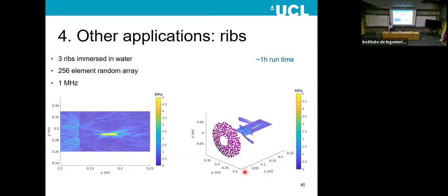It's a spherical section, but also you have 256 elements. Here they're all vibrating in unison, but you can introduce different phases and magnitudes to each element to produce beamforming effects. When you say element, you mean something that is produced? Piezoelectric elements, yeah, sorry. So there are little piezoelectric transducers, 3 millimeters in radius each.